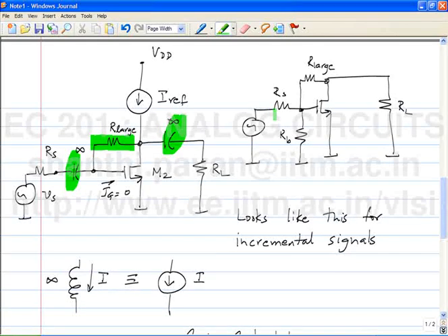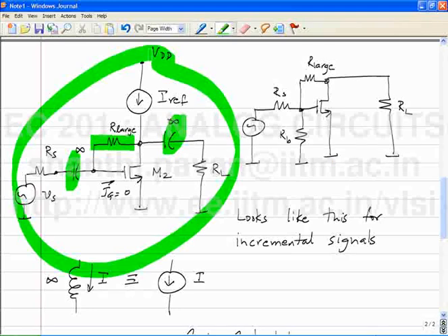It can go 1 VT. So definitely in this amplifier, the output swing can never exceed VT without the transistor moving to the triode region, which will cause the sine wave to distort. Okay, which side of the sine wave will get clipped off? The top or the bottom? The bottom of the sine wave. You understand?